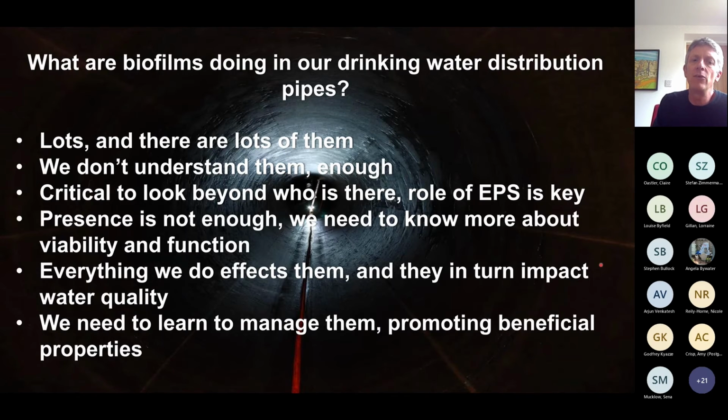Really important message, though: everything we do in our pipe networks, in terms of the hydraulics, the chlorine regimes, the temperatures, they all impact our biofilms, which in turn impacts our water quality. So understanding those coupling effects is really important.